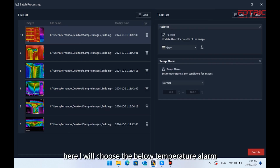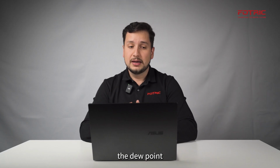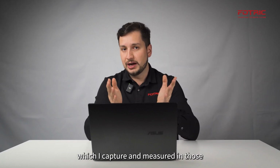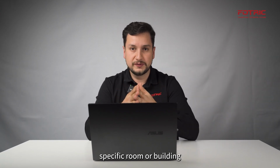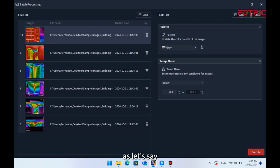Here, I will choose the below temperature alarm, and these images are right now in Celsius, and I would like to see the dew point which I captured and measured in those specific locations inside that specific room or building as, let's say, 12 degrees Celsius. That's going to be my dew point, and it's going to show all the potential places with condensation.